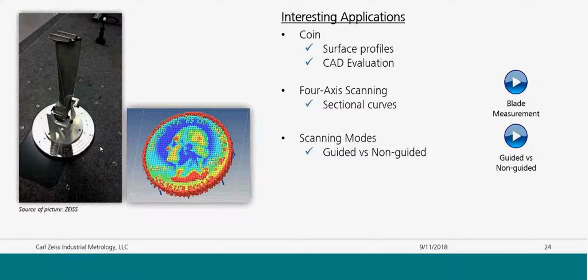And there are also different types of scanning modes with a sensor like this. Brandon hit on it a little bit, but one of the downsides with a sensor like this is you do have a pretty small measuring range to work with. What that means is if you have a large defect in a part and it falls below the measuring range, you're not going to get any light reflecting back up to the sensor because the focal points will all be in thin air.